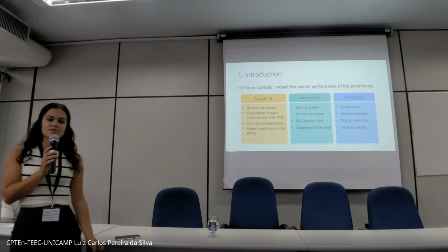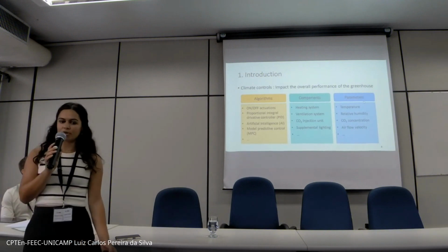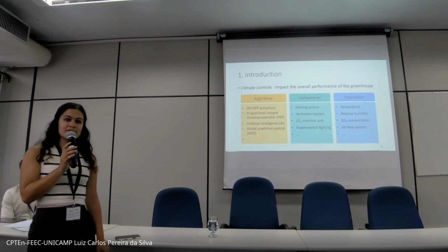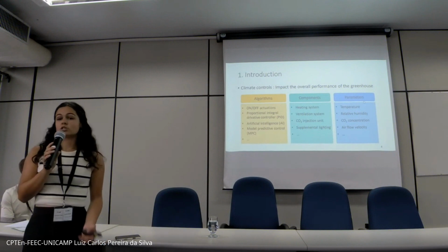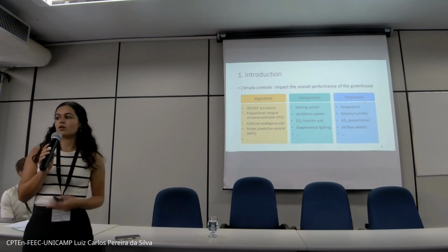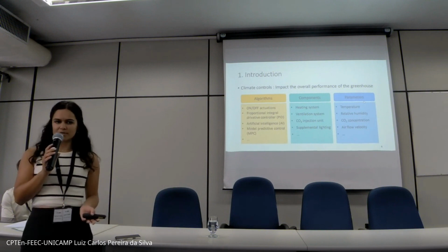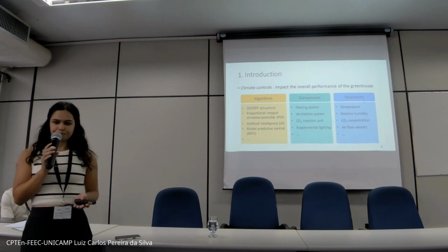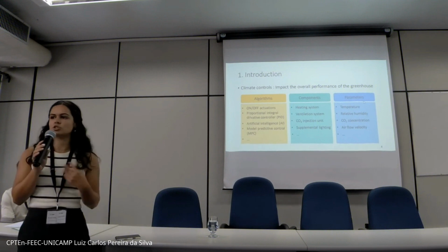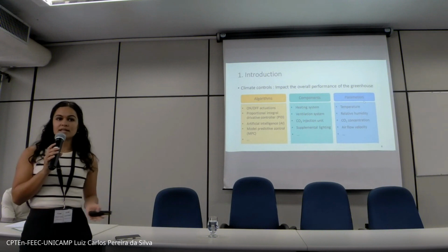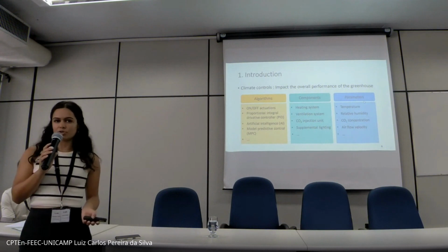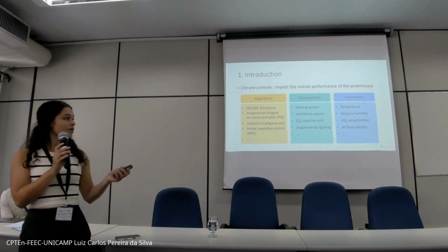With greenhouse farming, there is climate control. Climate control is a main part, and it will really influence the performance of the greenhouse. There's different algorithms that can be used to control greenhouses. Some are really simple. Manual growers will turn on and off different components, and we also have really intelligent algorithms. Each algorithm will use different components. So in a greenhouse, we'll have the heating system, the ventilation, CO2 injection, and different components. And each of these components will be set by different parameters, like the temperature, the relative humidity, and more.